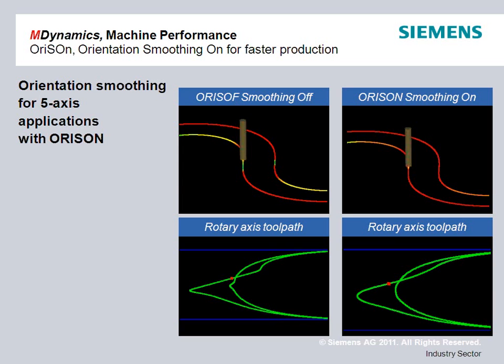We can also see down at the bottom that the green lines represent the 2 rotary axes and what kind of path we're asking them to follow. It's effectively a pair of points that are somewhere up the tool shaft. But what we're doing is taking a pair of sharp corners out of there. And because these sharp corners are gone, we're not going to see it in the wall of the part, and we can run faster. And conveniently, this is a very easy function to activate.